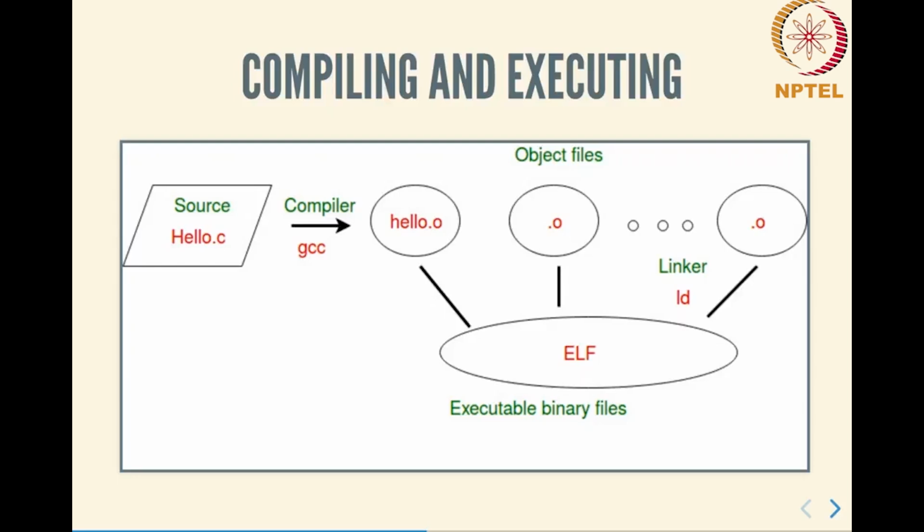For our purposes, the most important thing to keep in mind is we will be finally trying to run programs on another processor called the Microblaze. And in order to create the ELF files for the Microblaze, since we cannot compile directly on the Microblaze processor, we will be using something called a cross compiler that will run on your Linux system and generate ELF files that are meant to run on the Microblaze.